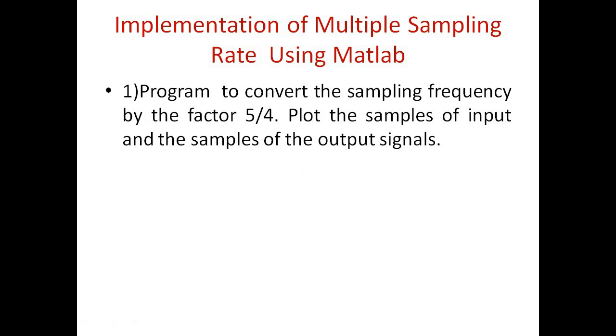But the problem we can infer in the analysis of the entire sampling rate conversion is that the rational factors are okay when we go for a lower range, but when the decimation factor is high, the interpolation factor also increases, and that is where we need to look carefully. So to visualize it: when the interpolation factor is more than the decimation factor, what influence will we observe? And if the interpolation factor is less than the decimation factor, what is the significance of the waveform which will be inferred?